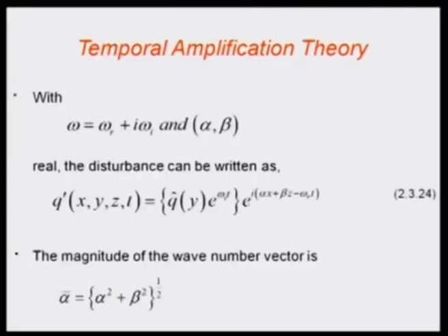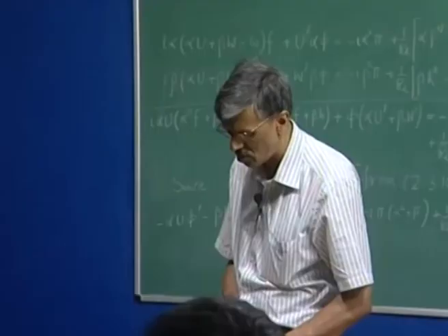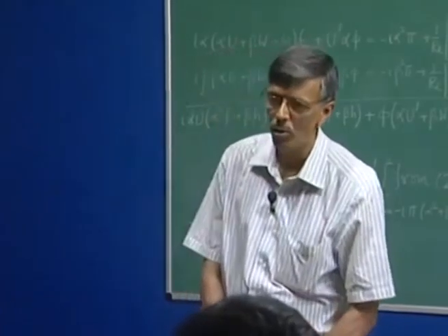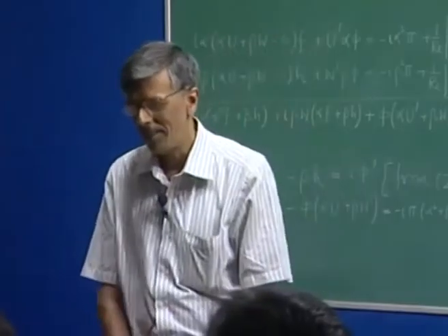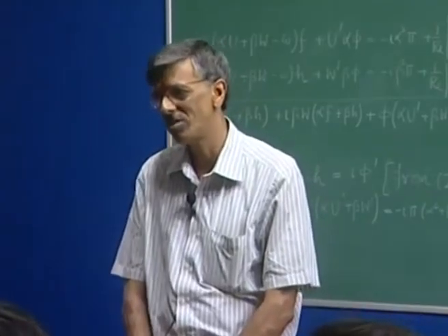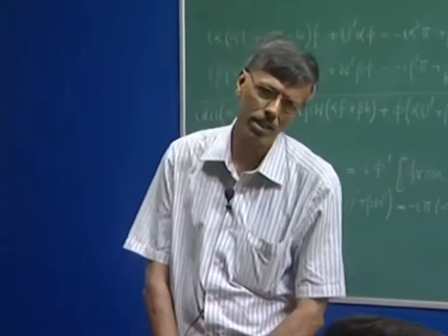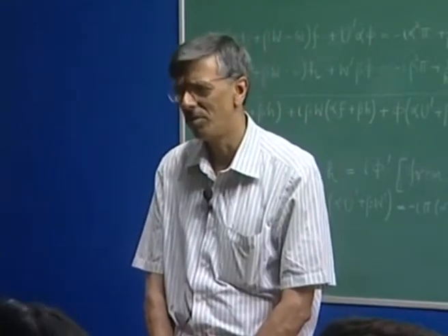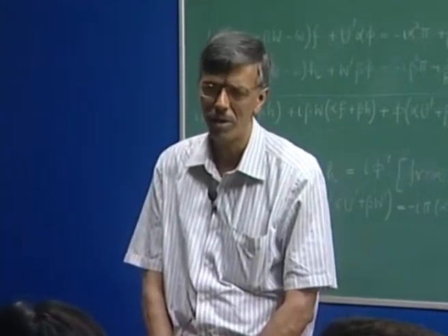Now, I would like to bring to your attention the attributes of instability studies. As I told you, ideally it would be nice to talk about disturbances which grow both in space and time. Despite that, we have classes of flows where we would see the disturbances grow in time, and there would be another class of flows where they grow in space. Give you a simple example, flow past a blunt body, like flow past a cylinder.